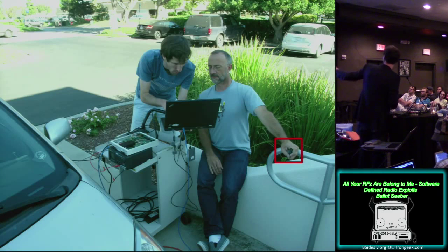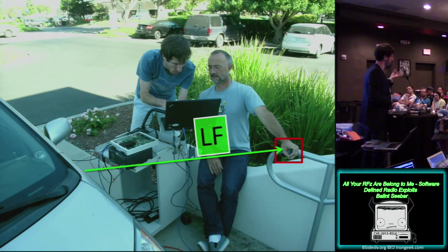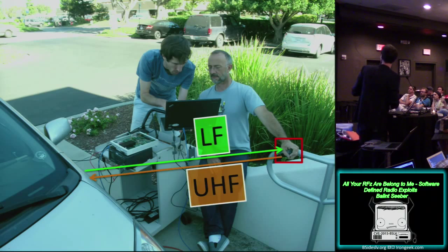So here, he has his fob in his hand, and the car is continually broadcasting a message over low frequency, and the remote control has a 3-axis low-frequency pickup, so that when you get close, it'll detect this message and then initiate a transaction, a challenge response. So the response is sent back over UHF, as it would be if you press the button on the remote control. But in this case, I just wanted to look at both sides of the link to see how that transaction actually took place.